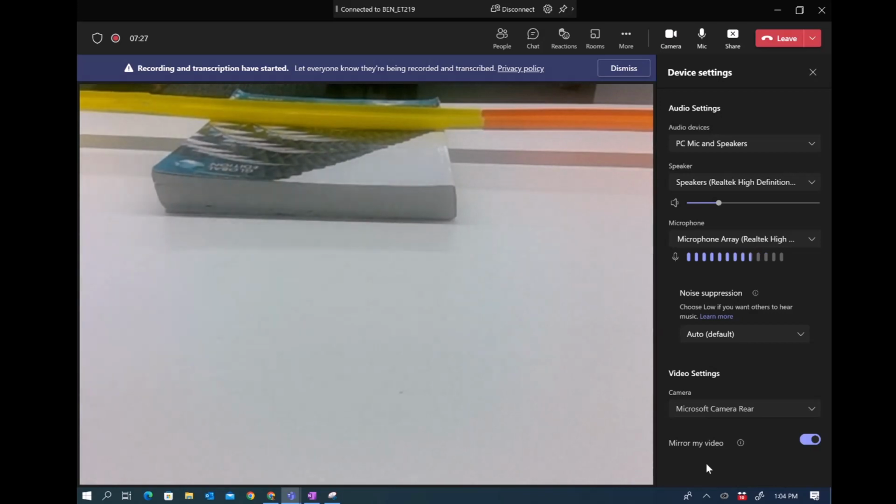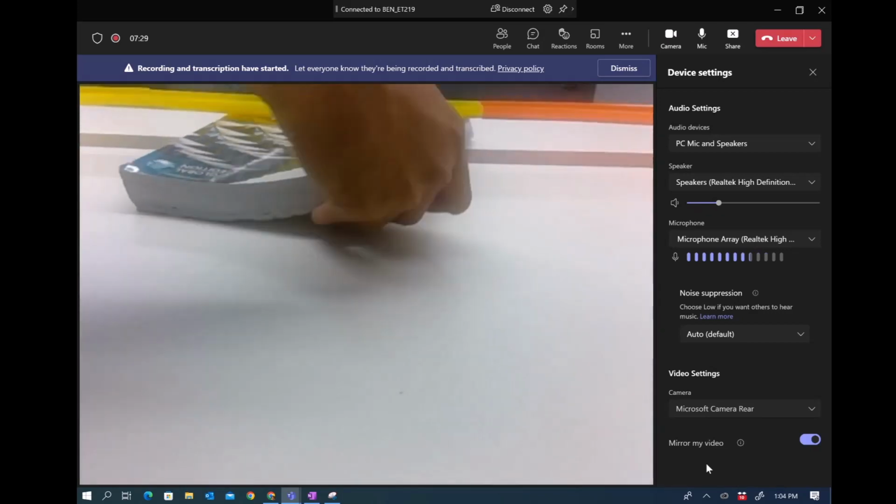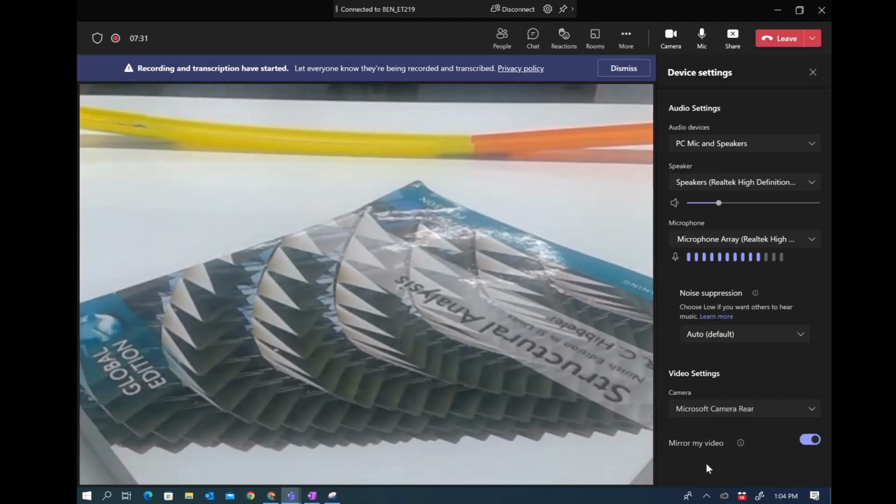How many extra forces do you have? I have 1 extra force. Let's remove it, because the engineer wants to make it simple. Everyone says, yes, that is better. The deflection is there, but I'm happy. It's a determinate structure. We call this the primary structure, as you know from the lecture this morning. And primary structures are determinate structures. Engineers are happy with the primary structure.